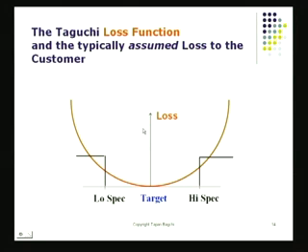What it really means is, for any quality you're looking at, there's always a best value that the customer wants you to have. If you're not quite there, you as the user or society at large will incur a loss, because that quality was not delivered at the target, it was delivered somewhere else. So the old idea of trying to control quality by looking at whether the product is within spec or not is not good enough.